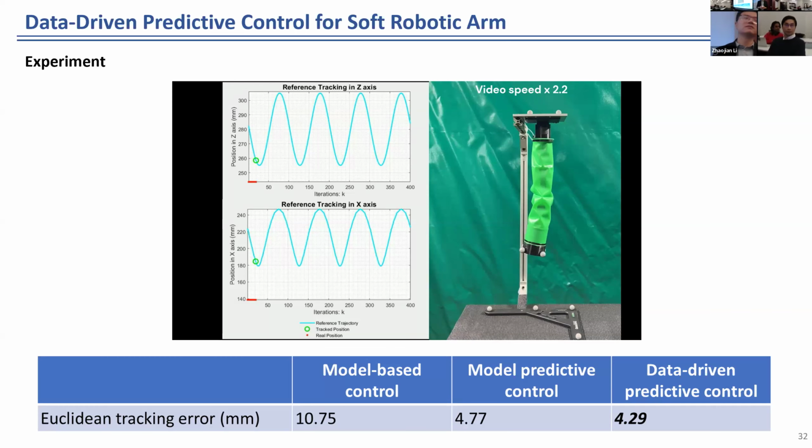So going back to the design of the custom arm, compared to, for example, an off-the-shelf arm, when you designed that, what was the decisive factor that made you choose this configuration of vacuum and pull rather than, for example, snipping or other forms of harvesting? Yeah, we tried a lot of mechanisms to pick the fruit. Right now we're using vacuum. We tried a soft gripper. We tried the claw design. In the end, we think that the vacuum is the best for the following reasons.